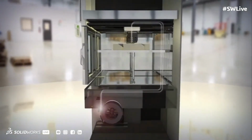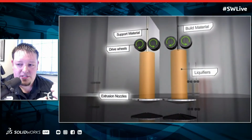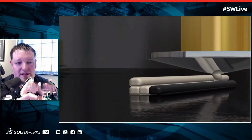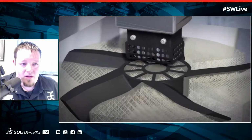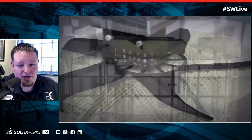To put it crudely, it's a CNC controlled hot glue gun. Basically, you've got one or two extruders sitting next to each other, and one of them is doing a support material. The other one is going to be doing a build material. The build material might be ABS, polycarb, or something like an Ultem or PEEK. And your support material is usually a water-soluble material that can be soaked away after the printing.